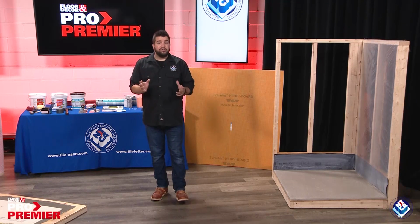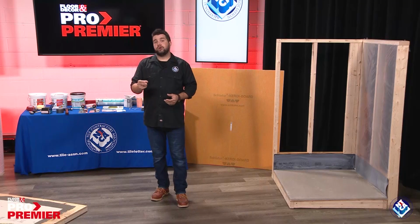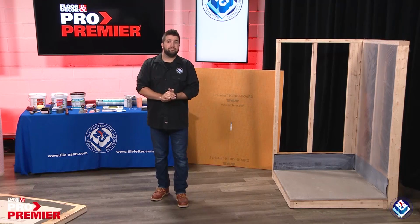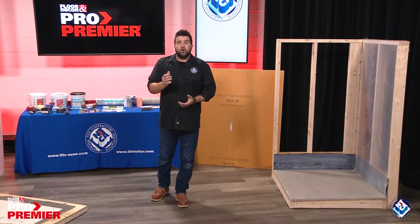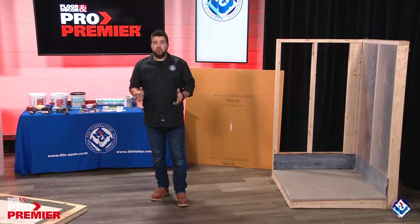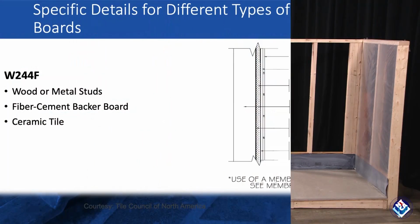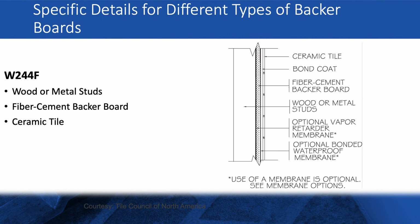This board may also be installed on exterior surfaces under method W244E, E for exterior. It is the only backer board in the group we are reviewing today which may be used outside. Let's move on to W244F, which is going to look very similar to the previous one.